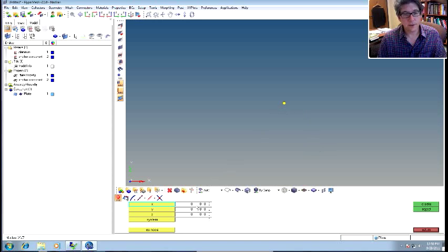So the next point will be at the radius is 2, so I put it at 2 there. Create, there's that point. The next point on the edge is going to be half the width. The width of this thing is 18 inches, so that's out at 9. Create that point. So we can also create the top corner, which will be at 9, and then half of 36.